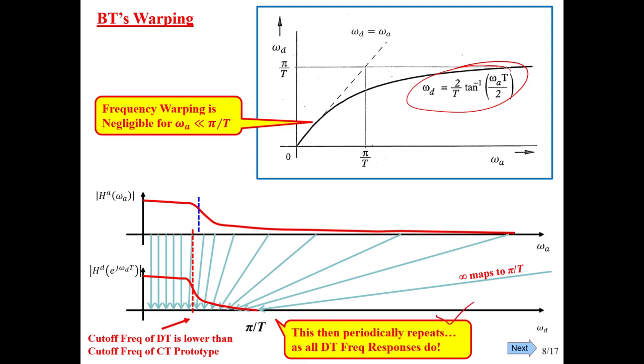And then I point out, remember, this frequency response doesn't continue on. Discrete time filters. So that's our 0 to pi range in the capital omega variable. And so it repeats periodically, which I'm not showing here, but we have to remember that that is there. It's not part of this mapping. This mapping just maps the full frequency response into the main region on the capital omega axis. And then we have to remember there is the periodicity involved.